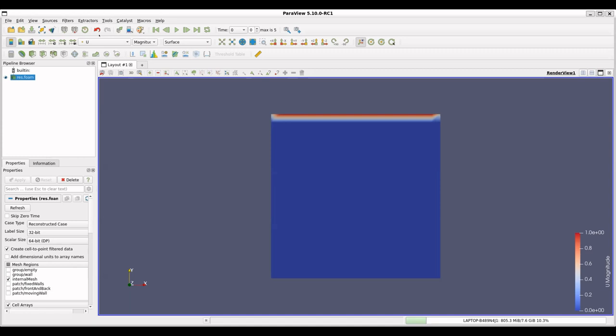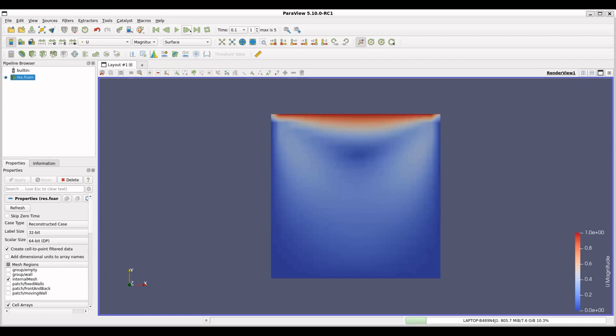There we specify 100, that means 1 meter per second in the x direction. So that's what it is showing at t equal to 0. Now, when I run just the next step of the solution, it solves all the grid points here and accordingly shows us the field variable of velocity in all the grid points.